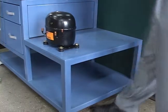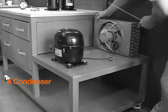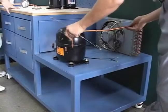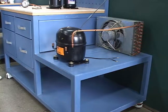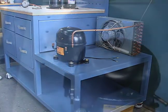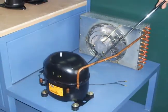After fixing the compressor on the table, the condenser will be fixed on the table. There are water cooling type and air cooling type condensers. We use the air cooling type in this test. The condenser exchanges heat between air and the high-temperature, high-pressure gas from the compressor and liquefies it into high-temperature, high-pressure liquid. In other words, it makes the high-temperature, high-pressure refrigerant gas from the compressor into low-temperature, high-pressure refrigerant liquid. After fixing the compressor and condenser, the piping of the compressor discharge and condenser part will be completed.